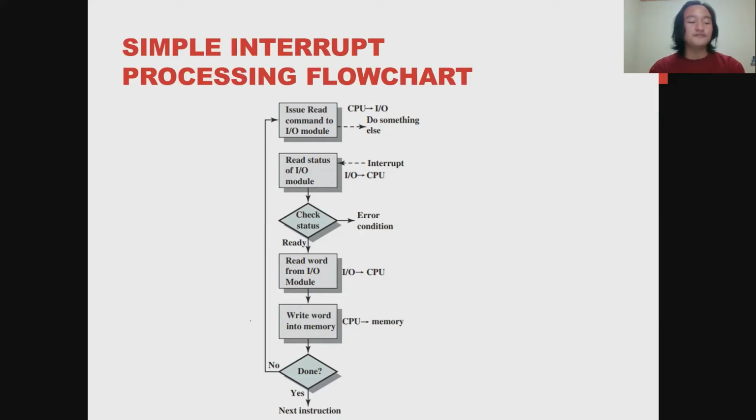The CPU receives the interrupt signal on the interrupt request line and transfers control to the interrupt handler routine. The interrupt handler determines the cause of the interrupt, performs the necessary processing, and executes a return from interrupt instruction. The CPU returns to the execution state prior to the interrupt being signaled. The CPU continues the processing until the cycle begins again.